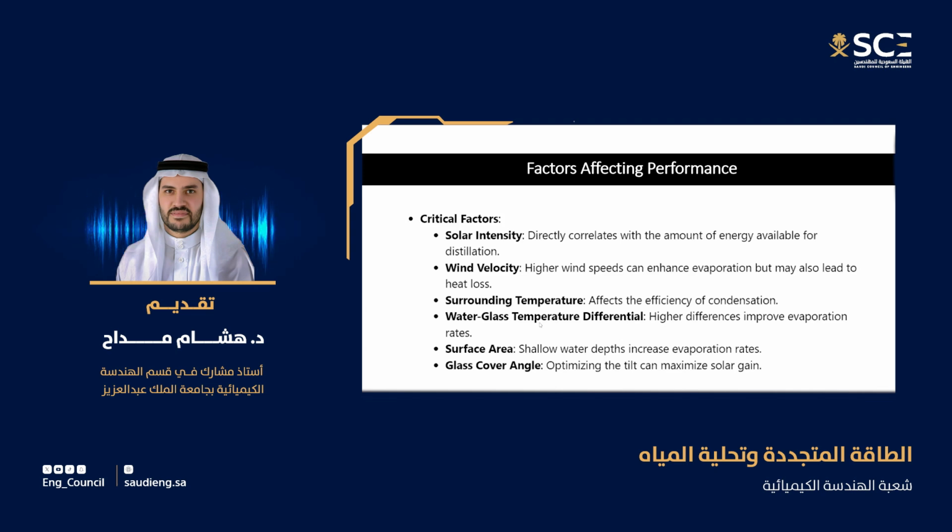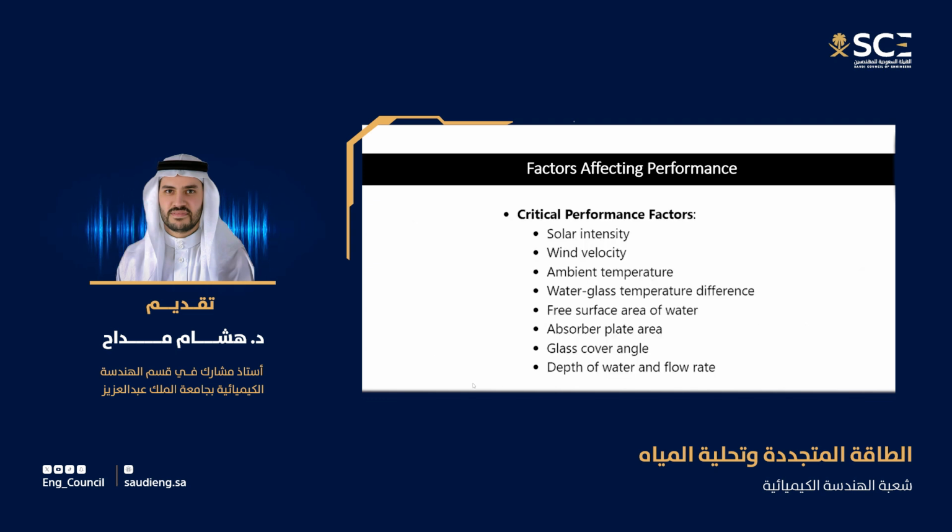The most important parameter is, we call it TG/TW. This is how much is the water temperature and how much is the glass temperature. The difference between them is gonna drive the heat transfer, and we call it heat transfer coefficient. The evaporation gonna increase if you have more differences between the water temperatures that is gonna rise from the solar radiation, and the glass temperature of the cover is gonna be less because it's not gonna absorb as the water.